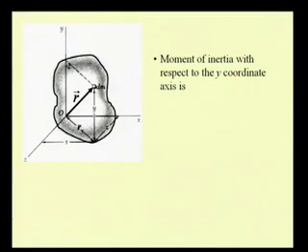So, if we know the second moment of a given mass with respect to the various principal axes, then one can also analyze the motion by considering these quantities along with the components of forces and torque in those principal axes. So, in that context we are interested to find the second moment about, let us say, the various principal axes x, y and z.